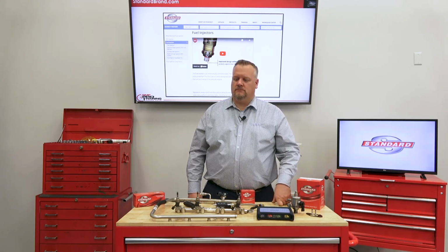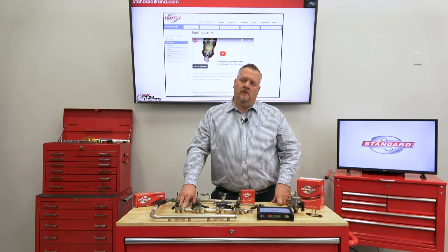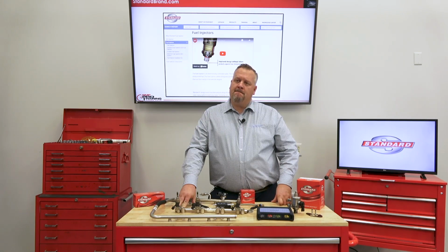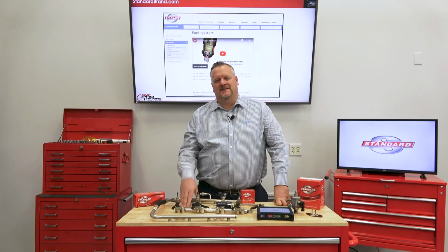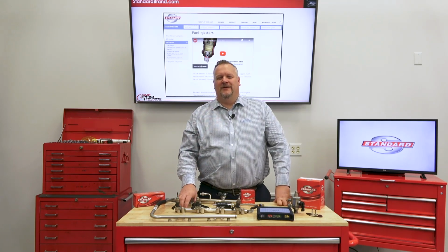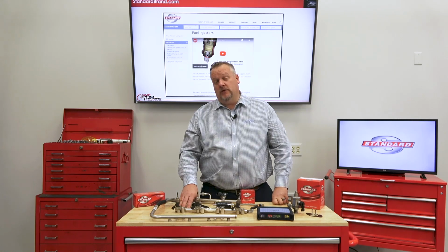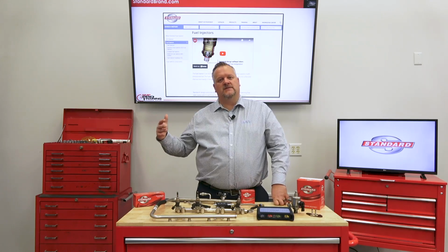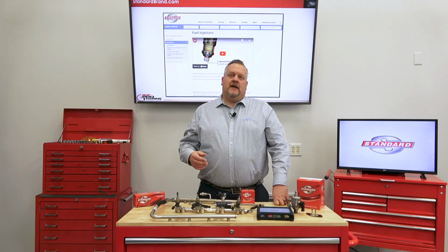Very good. And then I have 2 questions here that I'm going to put together for you. The first is, do all air fuel sensors report in Lambda? And to go along with that, do all GDI vehicles use air fuel sensors? Good questions. One thing we've learned in the automotive world is you can't say always or never. A lot of GDI vehicles are newer vehicles, and a lot of newer vehicles will use air fuel sensors, quite often in the upstream application, but downstream we're still going to see our traditional oxygen sensors in many cases. And then how do they report?